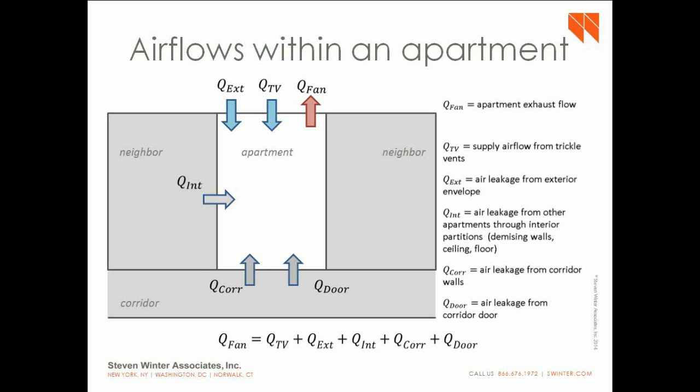And we've tested a novel PTAC unit with a fresh air kit that has a small fan that's supposed to pull air from outside through the unit and deliver it indoors. Finally, we spent a lot of time looking at passive vents. Passive vents include things like trickle vents and airlets and all sorts of other vents that are supposed to draw air in through the envelope.